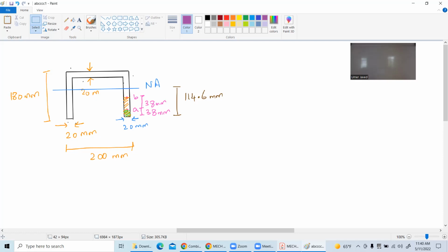So, what is I? I haven't covered it in class, but in this particular case, it is M R square, so ML square. You can double check ML square. So, it is M L square theta double dot. Now, you take them on the same side of the equation and we will see whether we have made a mistake or not. Plus ML square theta double dot equal to 0. Dividing through, theta double dot plus G over L sin theta equal to 0. For an unforced pendulum, this is the equation of motion. You were pretty close, but for the mass moment of inertia, it is ML square.